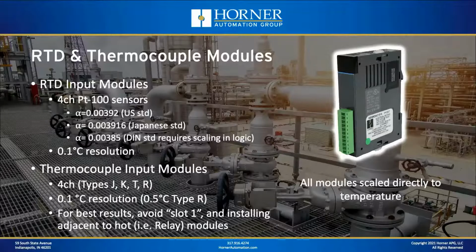Thermocouple modules of all kinds depend on something called cold junction compensation. That means the module has to measure the temperature of the IO plug so it can compensate for the cold junction of the thermocouple extension wire connected to the IO plug. You can get some error if that IO plug has hot spots. Normally not a problem.